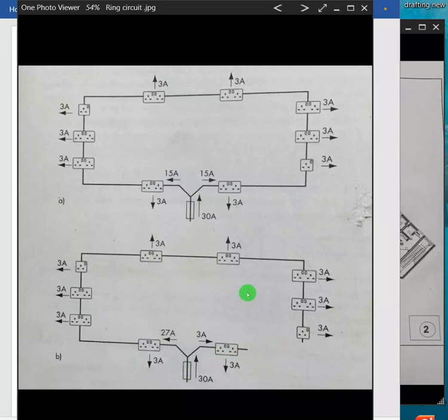That's the advantage of the ring. Until we have another open circuit at another point, making a second break, that is when one particular portion has a power outage, while the rest have power. Until we have two breakages in the circuit, that is when we have a full disappointment. But if we have only one breakage on the circuit, the entire circuit will still remain complete.